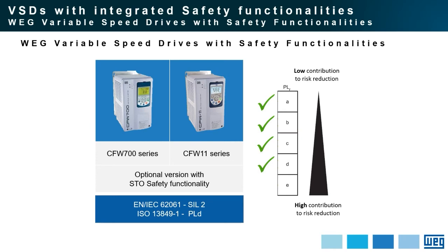Concerning IEC, it complies with safety integrity level 2, and ISO standard, it complies with performance level D. So these two variable speed drives can be installed in several applications, from performance level A up to performance level D, without the additional safety devices we spoke about before.